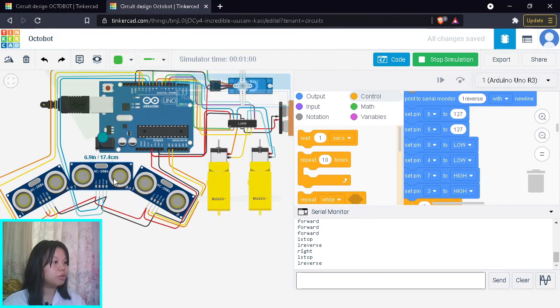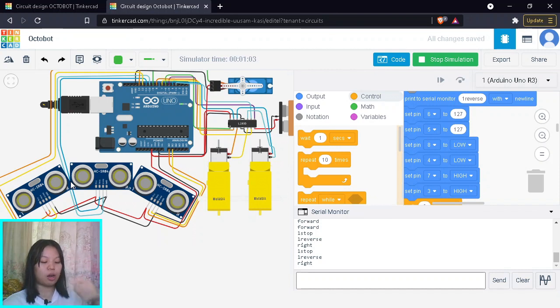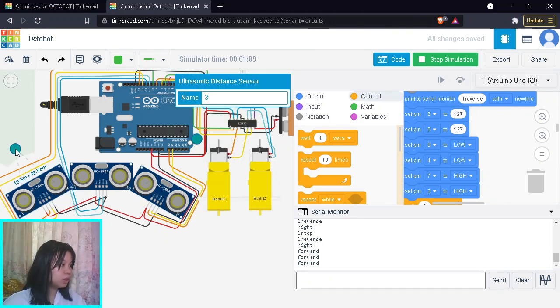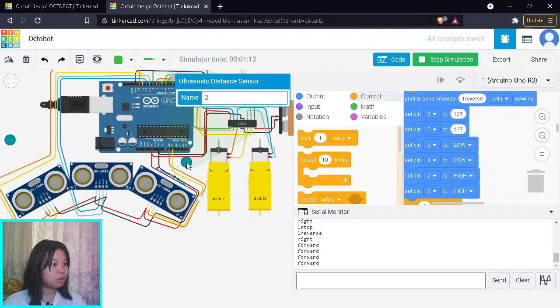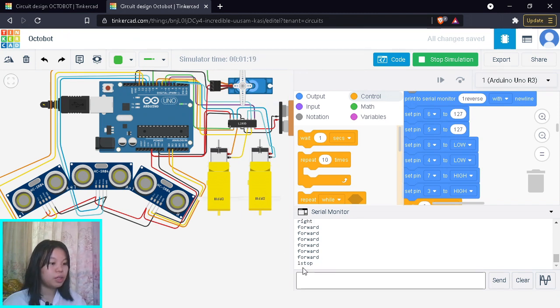Now we look at scenario 2 combined with scenario 4. After checking, the obstacle is not on the left, it's on the right, so we're going to steer and turn left. For that, I'm going to make left have no obstacle, and right have an obstacle, less than 20. So scenario 2 less than 20: it makes the first stop at 0 RPM, first reverse at negative RPM at half the speed, 117 RPM now. After checking, it comes into scenario 4 and steers and turns left, so both are moving forward at half the speed. That is scenario 2 combined with scenario 4.